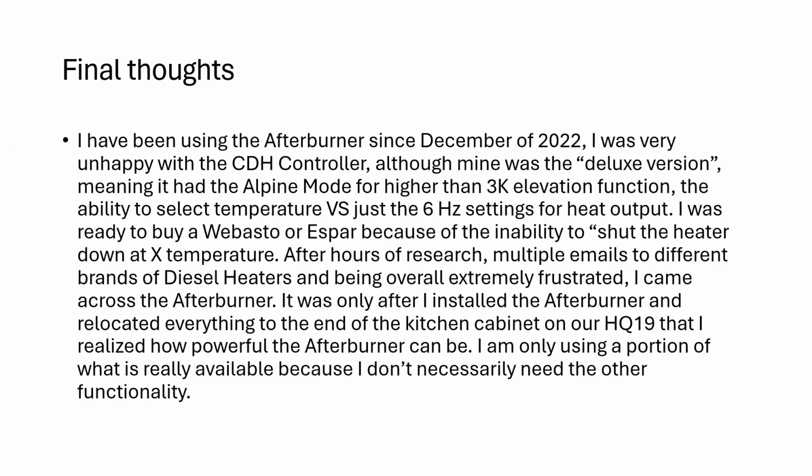I've been using the Afterburner since December of 2022. I was completely unhappy with the control that was with the Chinese diesel heater, even though mine was per se a deluxe version, meaning it had the Alpine mode for higher than 3,000 foot elevation and the ability to select temperature instead of just the 6 frequency settings for the output. I was ready to buy a Webasto or S-Bar because of that problem where even if I'm in the thermostat or temperature driven mode with the original controller, it does not ever shut the heater down.